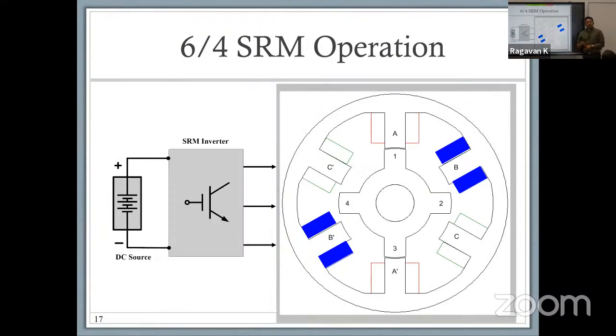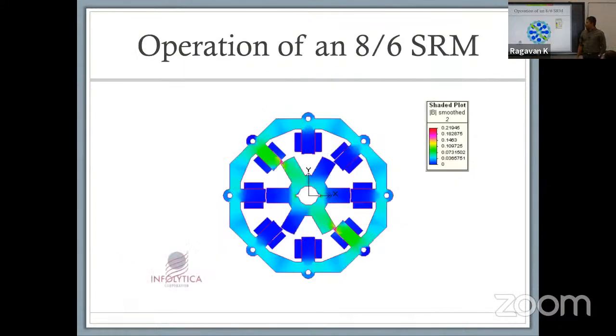All you're doing is identifying the sequence of excitation, and identifying the instant of time at which the current needs to be applied. Like I said, since the position is moving and it's a dynamic variable, when this position changes, the first thing you always have to remember is that if you energize the phase at the wrong time, you can get negative torque, right? It won't cause your motor to spin backwards, but you will definitely incur more losses.